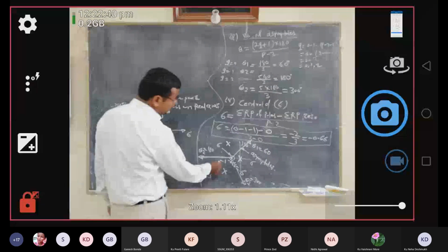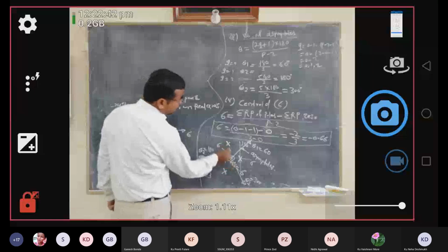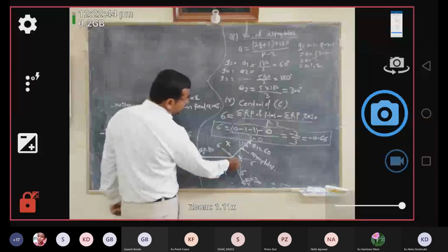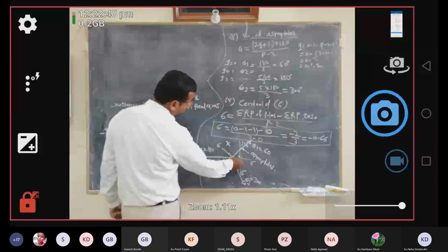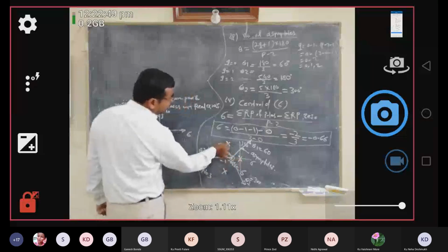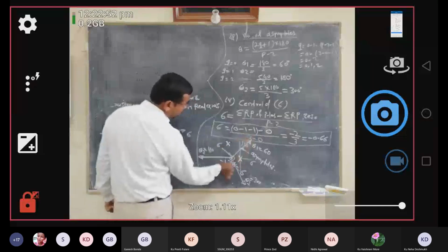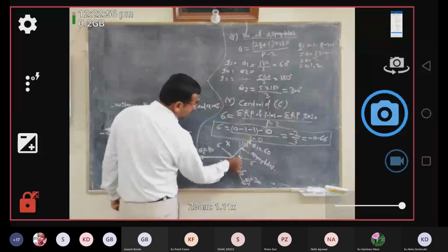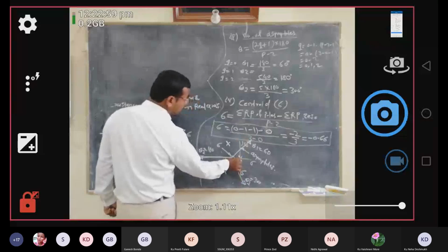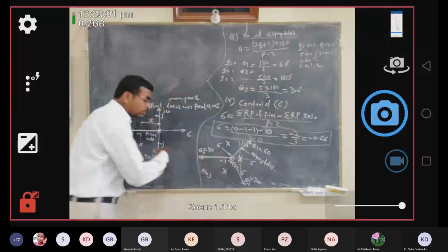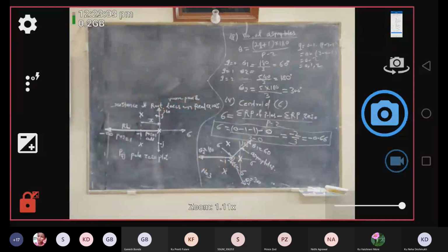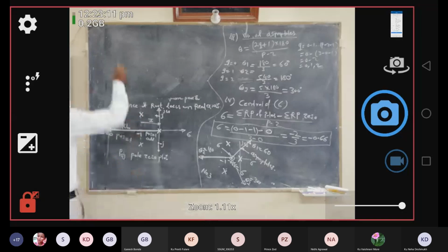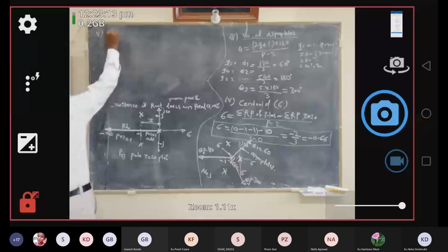So here in this case, your two branches will be starting at the complex poles and one branch will be starting at the pole at origin, and then they can terminate. So that means this pole's branch may terminate via theta1, this pole's branch originating, so this may terminate with theta3, and the root locus branch starting at this pole may terminate at theta2, like this. Okay, so that we will see. Then next step, step number 6, breaking point.